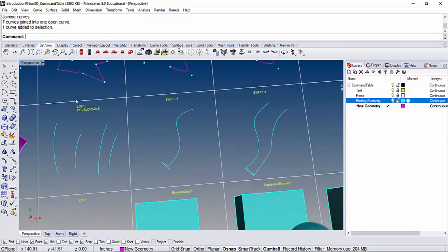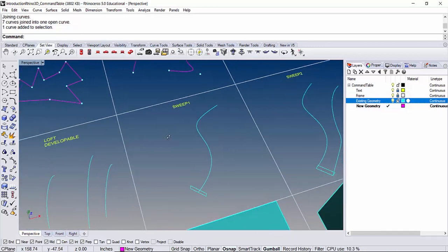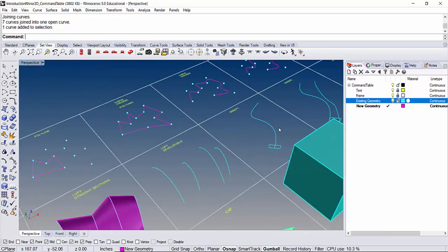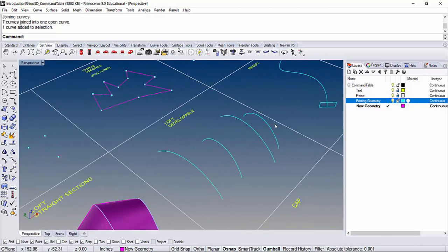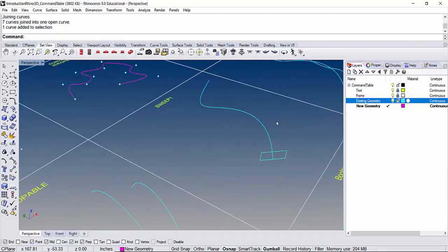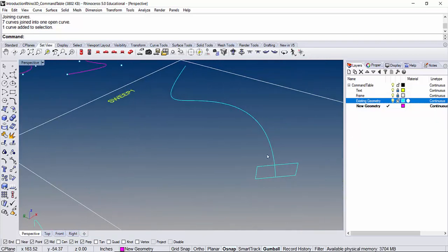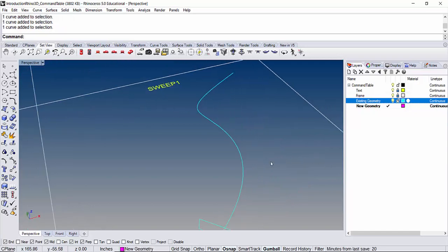So I'm going to skip this other lofting option. We're going to go to sweeping. Sometimes you have a series of segments like this. These are profiles that you'll be connecting and you'll be creating a surface. But sometimes you have another type of curves that you want to use to create a surface. For instance, the concept of sweeping. This is similar to when you have, maybe, a stair railing, and you have a profile that you want to then continuously use to create a surface.